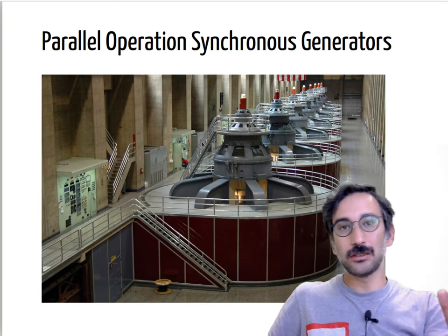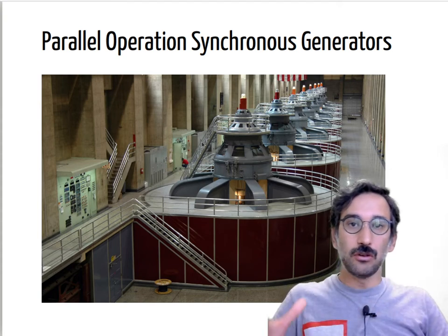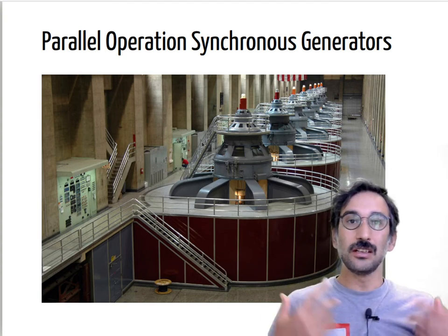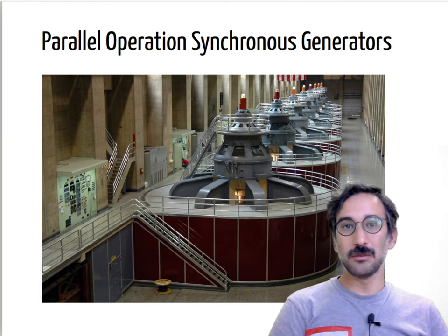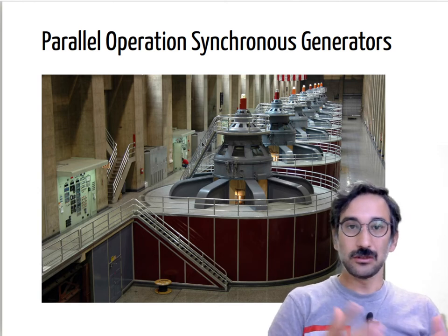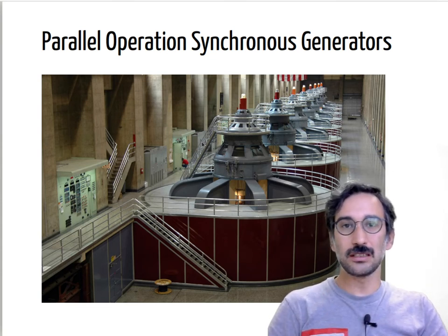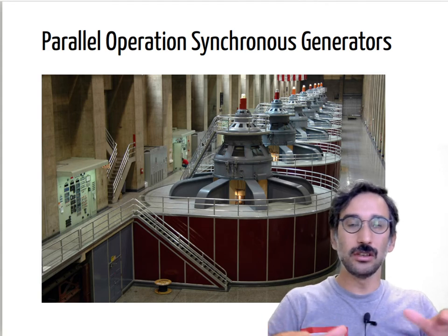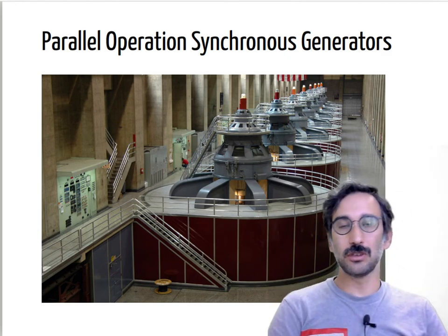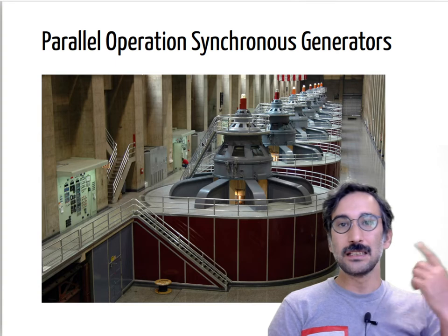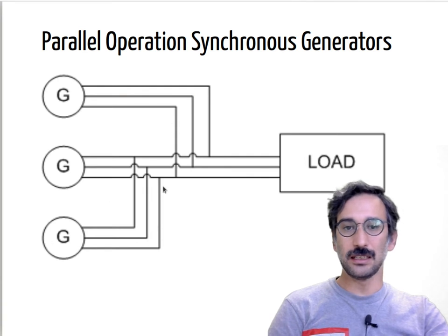Actually, it is not only about those generators. All of the synchronous generators in Turkey are all connected to each other. They are all rotating at the same synchronous speed. They are all supplying power to our cities, and it's not only our country. Turkey is also connected to the European system through the Greece power grid. So basically all different countries are connected to the same AC system if their voltage and frequencies are the same, and the generators are all rotating at the same speed as that system.